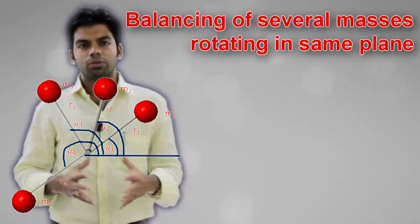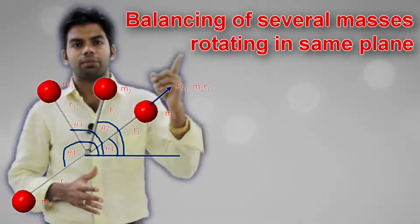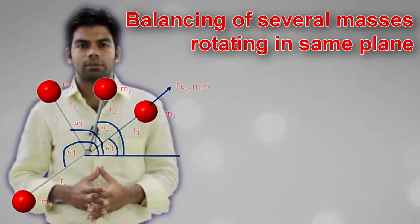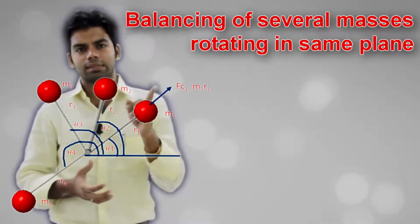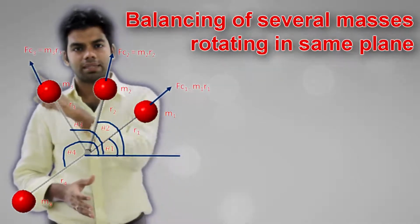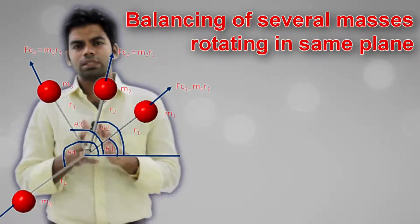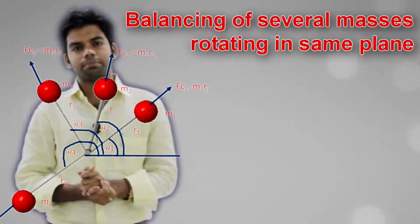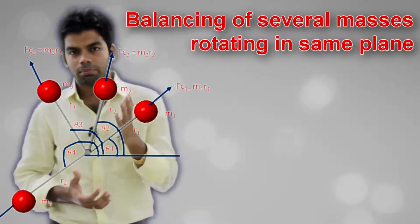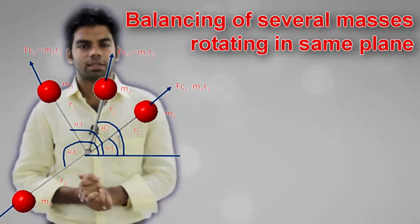Okay, now as I told you, these unbalanced masses will produce centrifugal force in outward direction. So this mass m1 will produce a centrifugal force Fc1, which is equal to m1 omega square r1. But because omega square is common, we will take it just as m1 r1. Similarly, mass m2 will produce m2 r2, mass m3 will produce m3 r3, mass m4 will produce m4 r4. Now first thing will be to determine the resultant of these unbalanced forces, and once we have determined the resultant, we can put a balancing mass in just the opposite direction of the resultant of unbalanced mass.